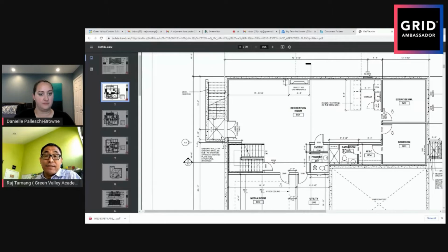Exactly. And nowadays it's called a stormwater management system, right? Because you build this new structure, it's going to create additional runoff. When it's raining, because of all this big impervious area, the water runoff would be higher. So you have to try to contain it inside the lot. That's why you have to build some infiltration drains, planter boxes, or a rain garden. Those are the stormwater management systems you have to accomplish within the site, right?